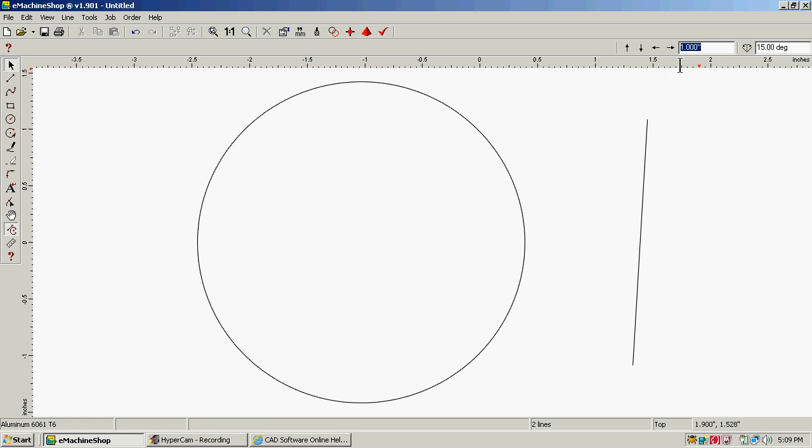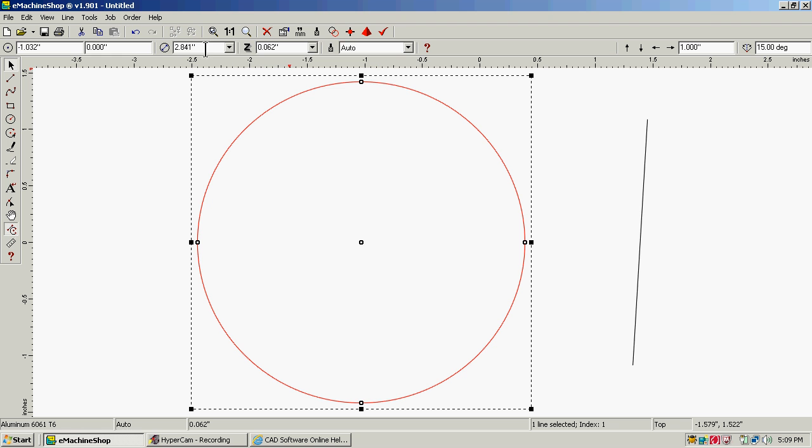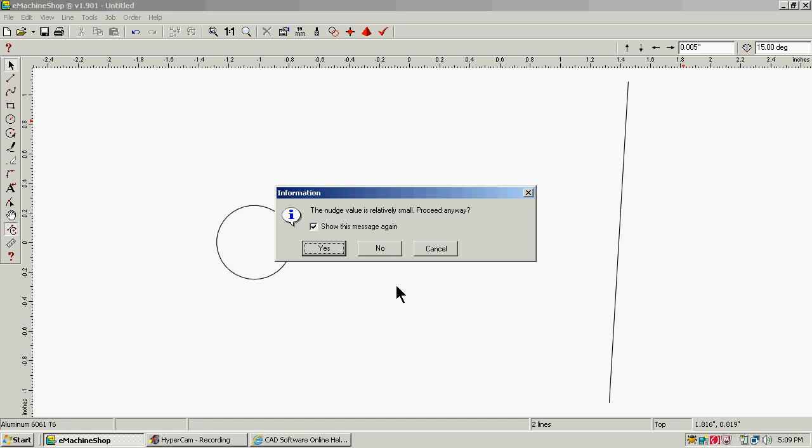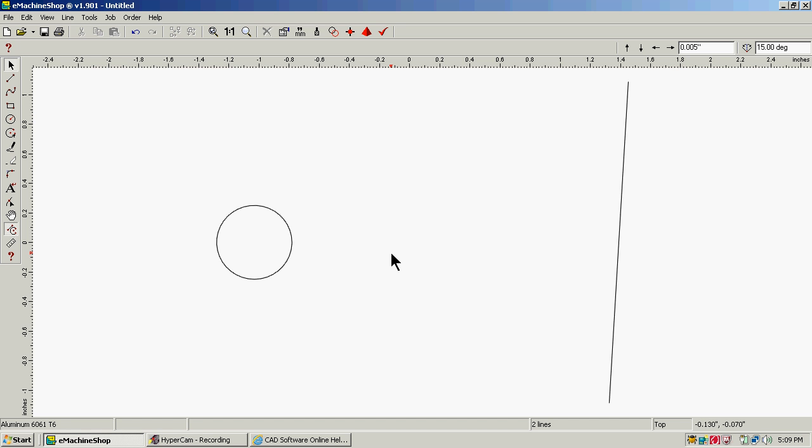There's also other uses. Let's make this circle smaller. Let's just say that it's a 1/2 inch circle. And I want multiples of these, and I've showed you before you can hold the Control key and then hit D to copy something. If this is set in like 5,000 increments, what'll happen is when I hit Control D, it's going to pile them all up on top of this circle, and you really can't see how many of them you've got. You can tell you've got them.